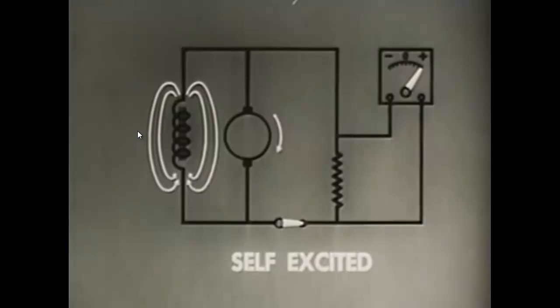Okay, so if you want to try it, it will work. It's very, very, very simple. It's not hard at all. It does work. You can short the armature winding. Now you've got to think that the car alternator is a little bit different. The alternator has a rotor, has a field winding on the rotor coil, has brushes that come out on the rotor itself. The armature winding itself is actually on the inside of the rotor itself. Now I'll pause and we'll get a quick image of this so we can see what we're talking about.